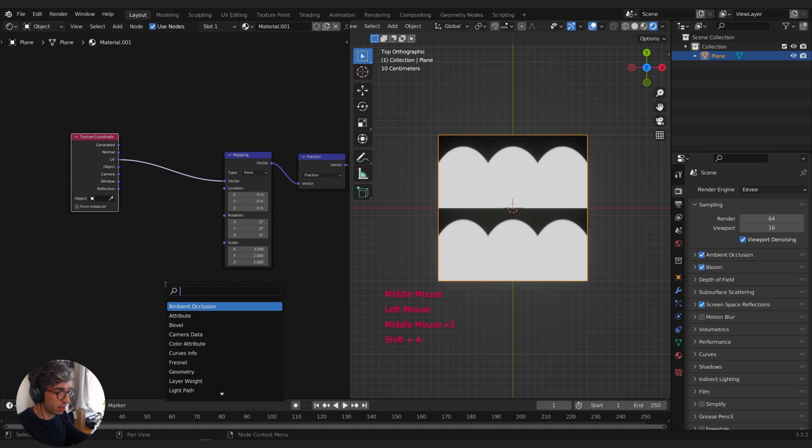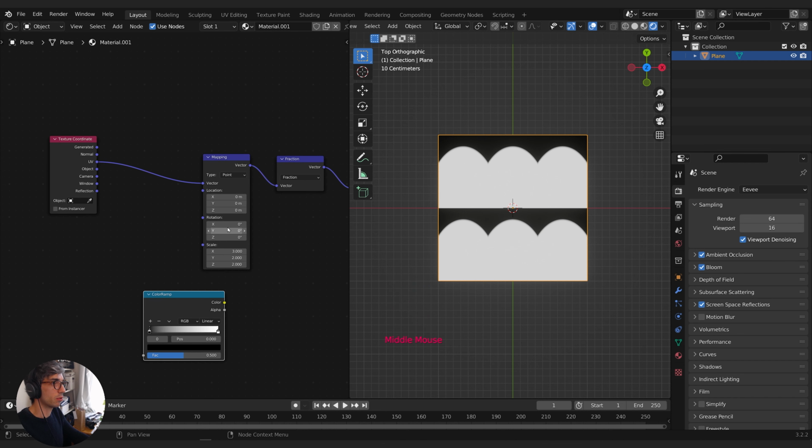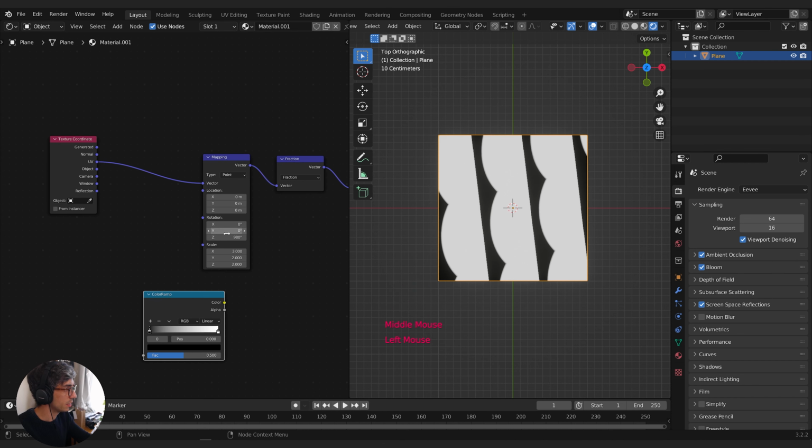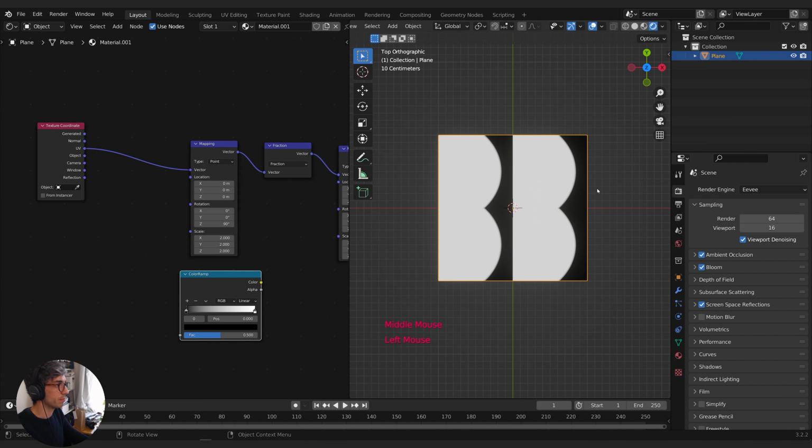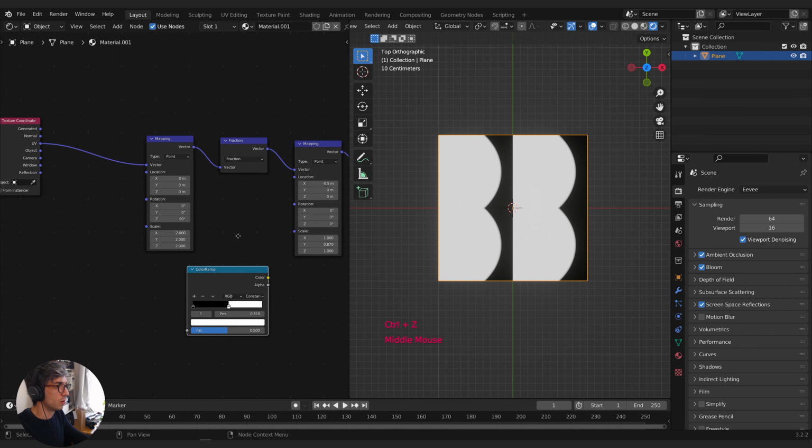So think about it this way. Let's create a color ramp. Okay, and I'm even going to rotate all this 90 degrees so it's even clearer to think about. And we will just keep this at 2, keep it really simple visually. So look at this color ramp, see how it lines up here with the direction things are going. I'm going to set this to constant, and I'm going to kind of drag this into the middle. So basically it's like I want to take everything that's on this side, this half of the object, and I'm going to move it 0.5 in one direction. So I want to move it, I think on the X, 0.5. So I want it to be like this. Whereas everything over here, this side of the gradient, I don't want to move at all.